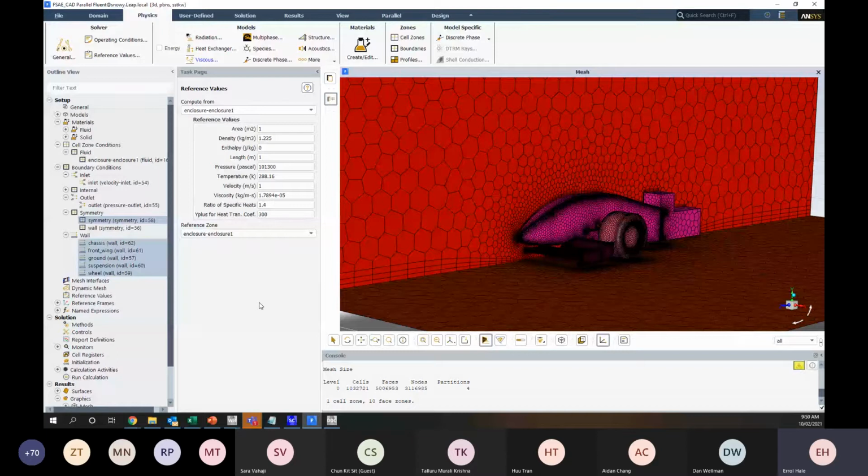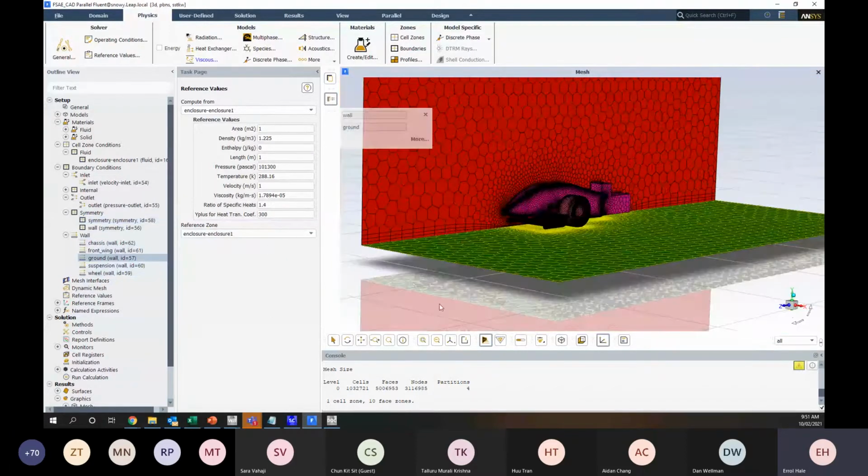Generally, to get the flow field fully developed, you'll need some space away from the inlet to allow that flow field to develop before it hits the vehicle, before it hits the region of interest. But a fully developed flow field straight at the inlet will usually require something a little bit more than just a pressure or a velocity inlet.